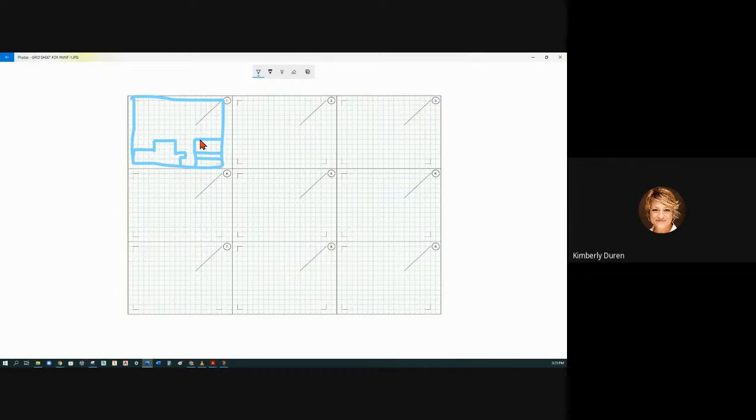And you've got to count the number of squares for its depth. So the depth on this is going to be the same as the depth in the top view. So there's my, using my miter line, here's how wide this part is. So I'm halfway there. Now I have this step right here.